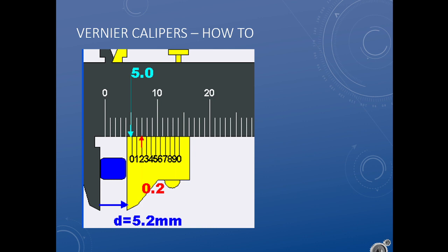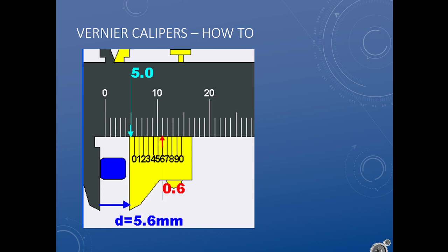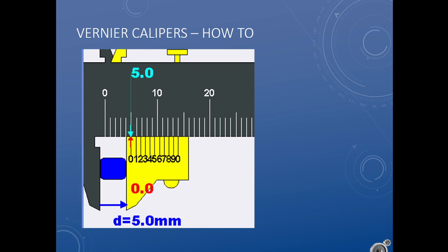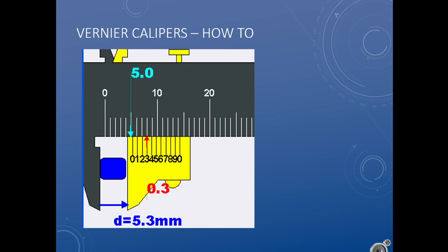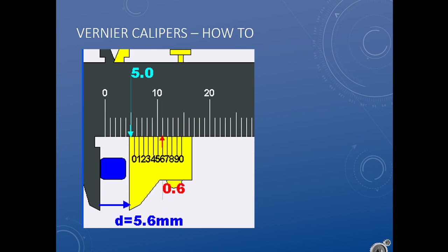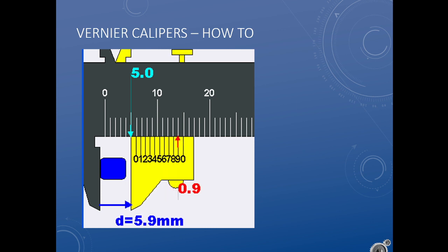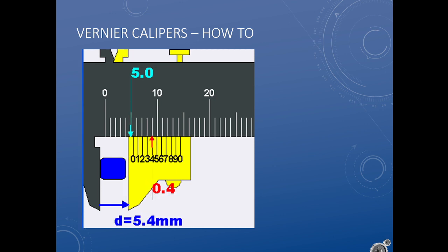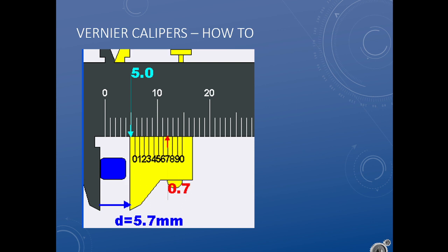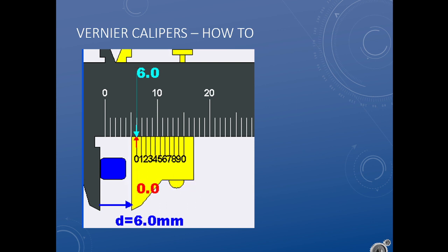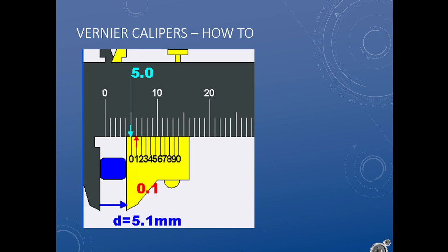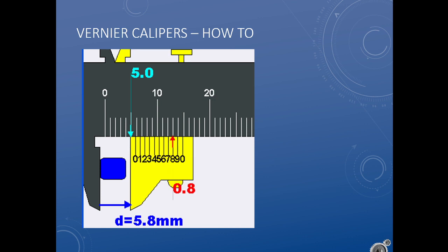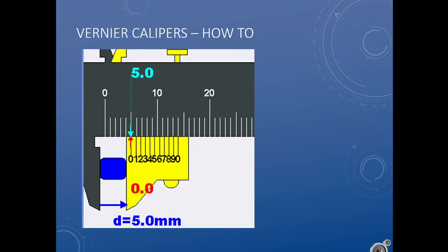I made a very big Vernier scale. All right, so 1 inch. And you'll see none of the others are lined up. Our quarter, our 2/4, our 3/4. These ones don't line up, but our 4/4 does, because that's 1 full inch off, right? And you'll notice there's 5 ticks here to 4 ticks up above. That is the wizardry of the Vernier scale. Just having one more evenly spaced tick below than above.